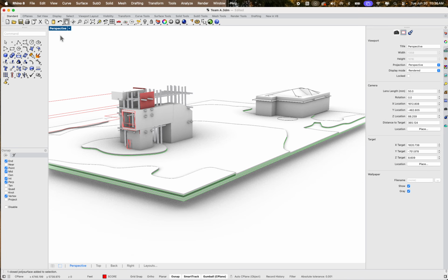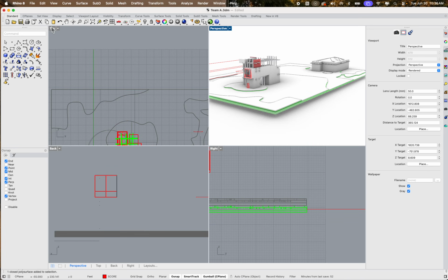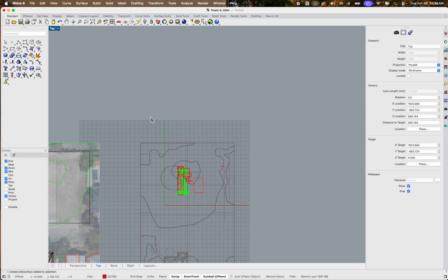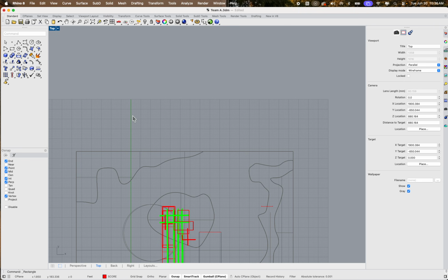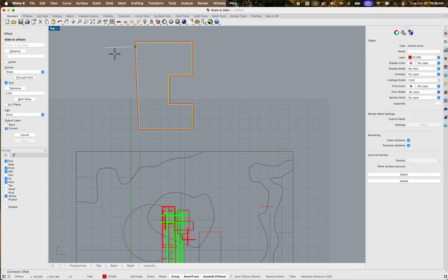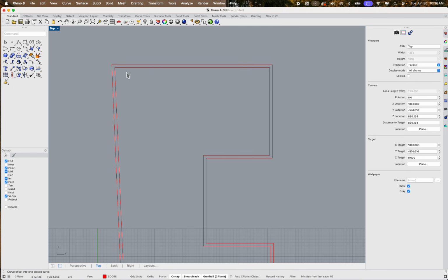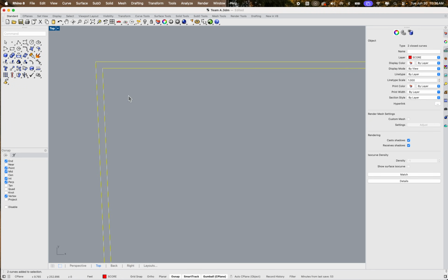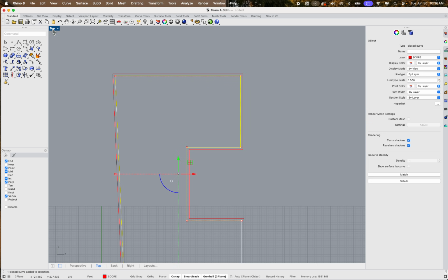What time is it? We're making this kind of a long one, so let's end it on a good note. Let's make a foundation. Arguably, again, kind of the exact same method. So if I had a polyline, let's say my foundation was like this, maybe something like that. I don't know, maybe it's weird like that too. I'm going to take an offset of 12 inches. When in doubt, offset 12 inches, right? I'll basically take this piece.